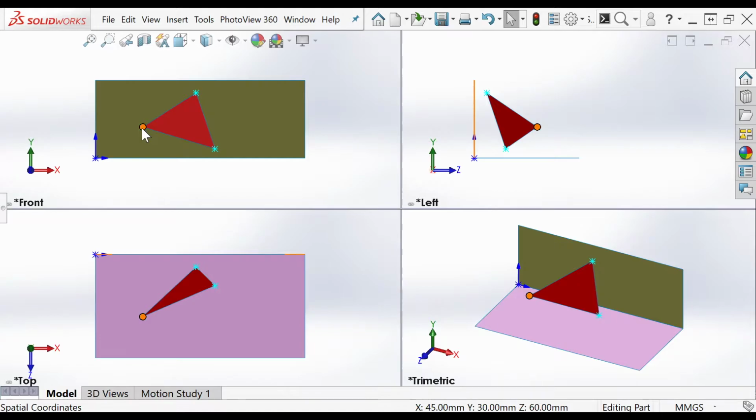So that's how far out down from the xy line it is. So our first value, x, is the distance in from the left. Our second value is its altitude above the horizontal plane, and our third value is how far it is down or out from our wall, so how far we'll measure down from our xy line.